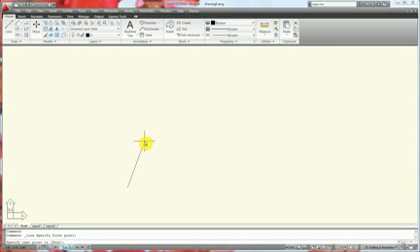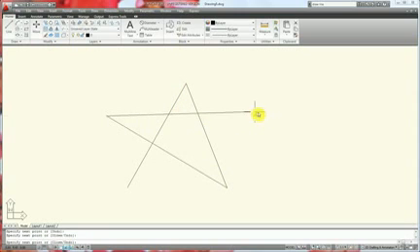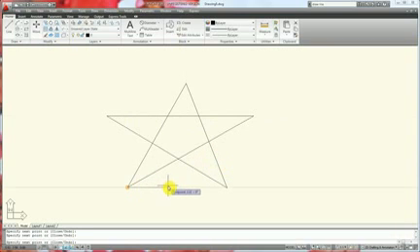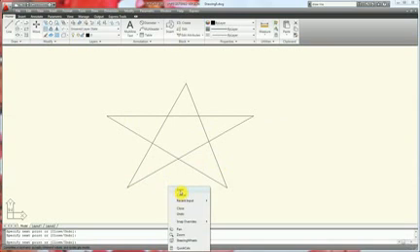Notice now I don't have to drag the line, I'm just moving my cursor to a new location to specify the next point as prompted in the command prompt line. So I'm going to left click this point. I'm going to go down here again. I'm going to kind of just draw this as best I can by just eyeballing it. When you're done, I'm simply going to right click and choose Enter.